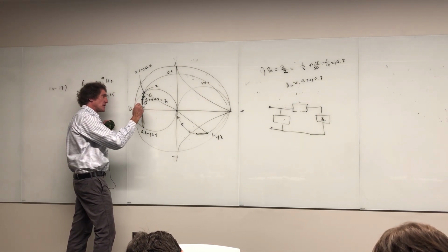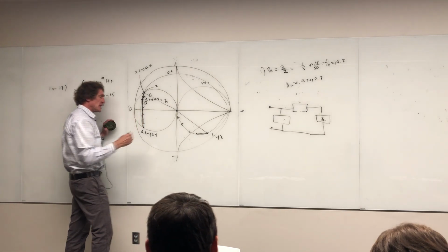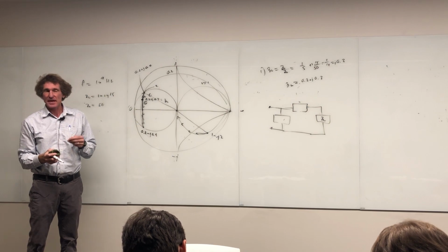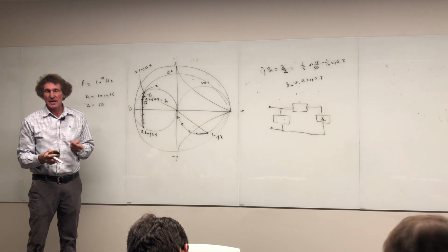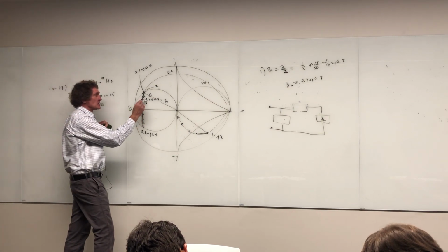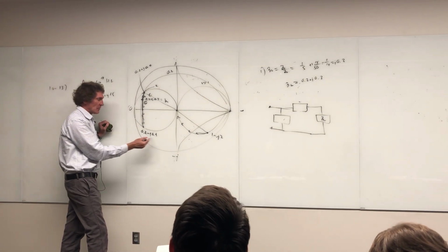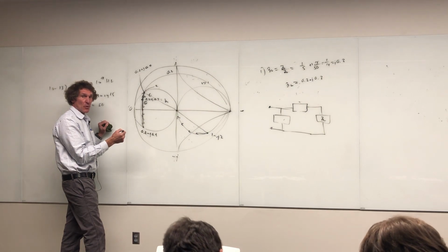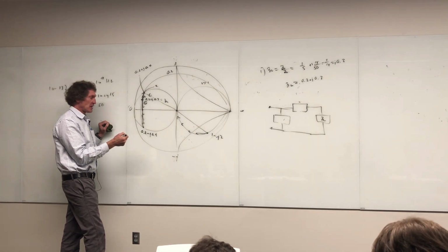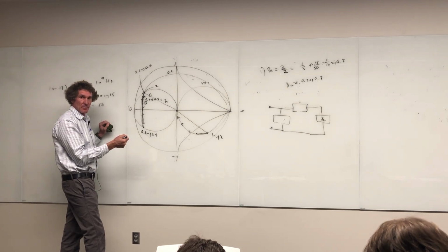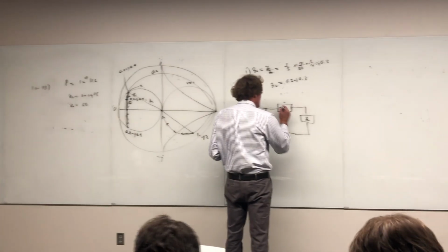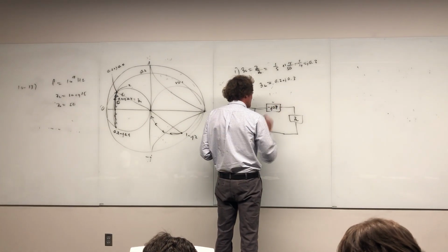And now I'm going to move this way. Now this is impedance. If it's a negative impedance, minus j impedance, that's a capacitor. Correct, class? How far did I move? I started at j0.3. I went down to minus j0.4, correct? I added or subtracted minus j0.7. Agreed? Everybody? So here, this is minus j0.7.